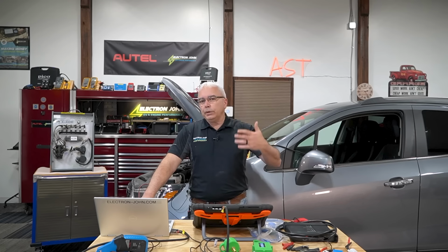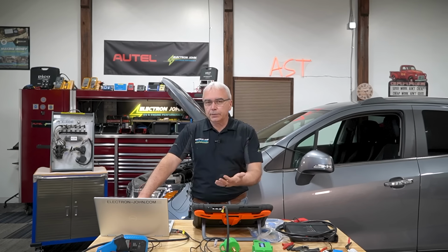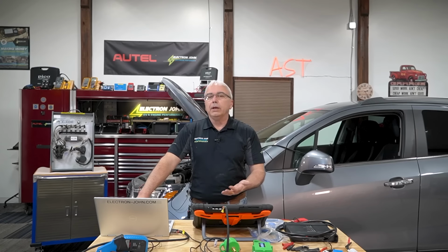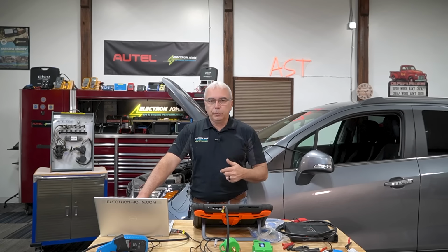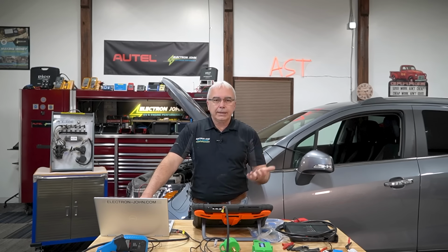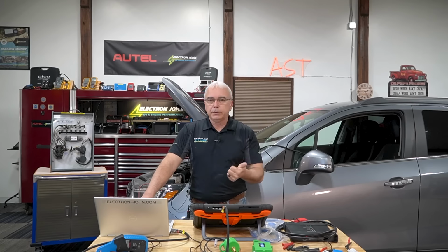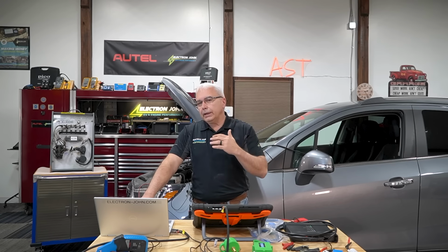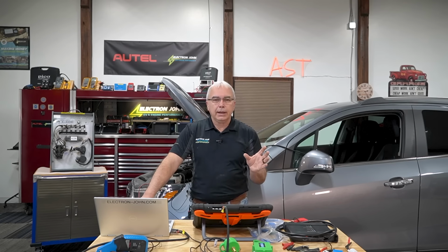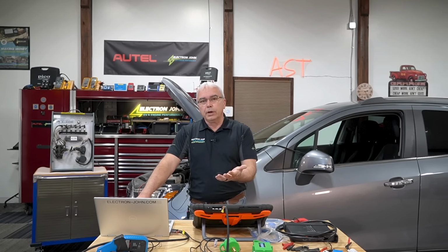So in open loop, it's when the car is first started, that oxygen sensor has to heat up to about 600 degrees Fahrenheit before it's ever going to go into closed loop, right? So in open loop, let's say, we're going to be looking at key inputs. So those key inputs are going to be a temperature sensor, throttle position, load sensor. We're not looking at an O2 sensor input because we're not even using the O2 sensors during open loop operation.